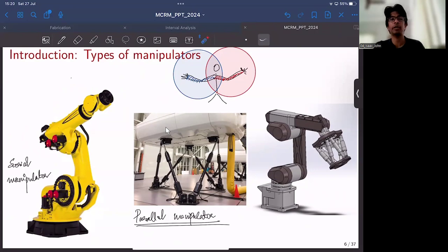But what happens if you try to reach a point when you grasp both of your hands? That will be much more limited compared to one of your hands being fully stretched, right? The reason is that if you try to plot the workspace when both of your hands are combined, for example, this being one hand and this being another hand, the overall workspace would be very small. The reason is that in the case of a parallel structure,